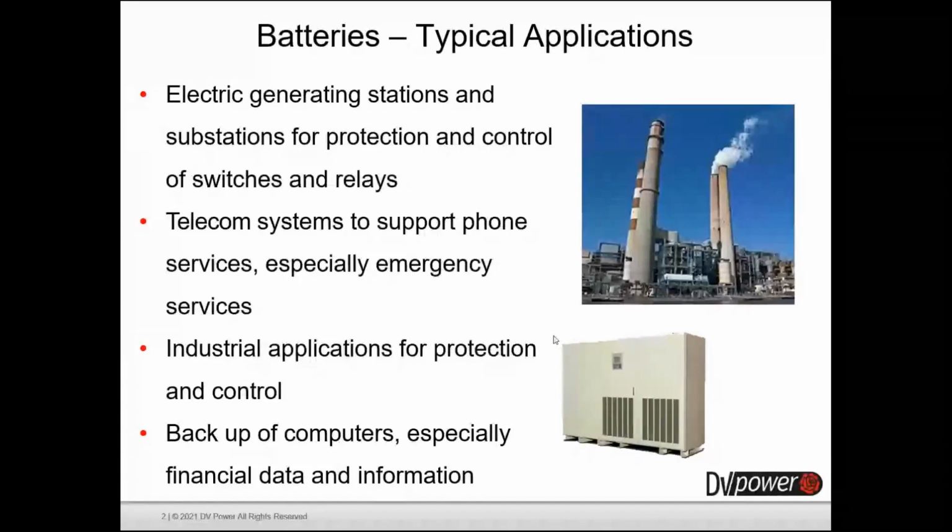And the best test of the batteries is the discharging test, or the capacity test, as we call it. The capacity test consists of two parts. The first part is a discharging test, where we discharge the battery to measure its actual capacity. At the end of every single test of electrical equipment, we need to have functional equipment.